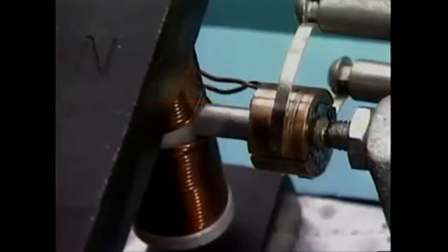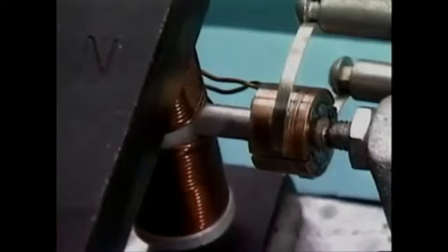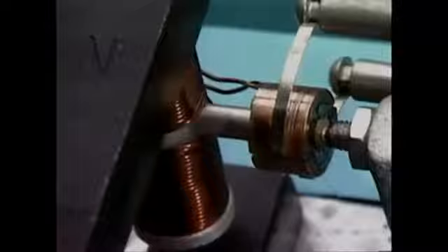When the motor is operating, current flows from the negative side of the battery through one of the brushes, then through one half of the commutator and onto the rotor. After the current flows through the rotor, it flows to the other half of the commutator, then through the other brush. And finally, it returns to the positive side of the battery. The commutator and the brushes constantly change the direction of current flow to the rotor. That's what changes the polarity of the rotor.